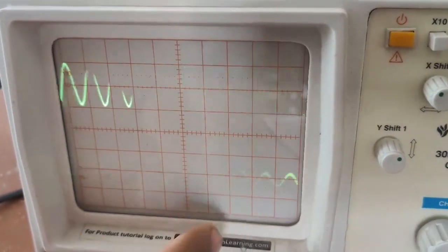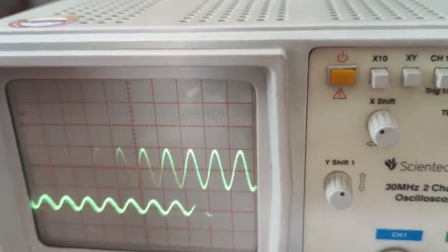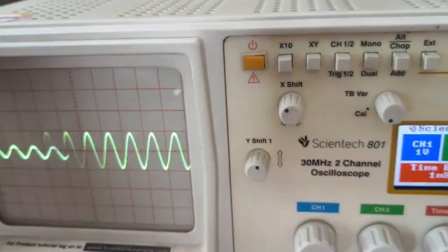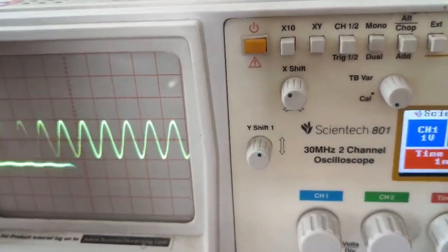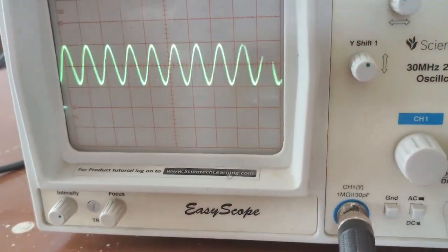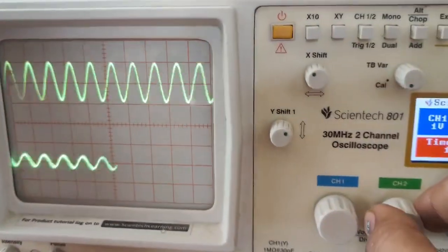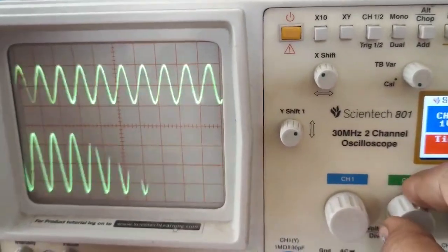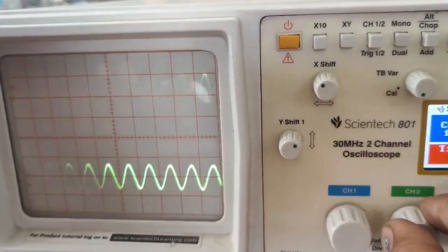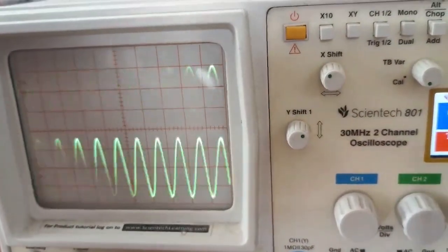and the wave over here is phase shifted. You can see this if you want. So if you bring this together, you can see there is a slight phase shift. So now to take the readings, you adjust it to the origin, and then you increase the amplitude of channel 2, at your convenience. So I am adjusting it to, let's say, 0.2 volts.